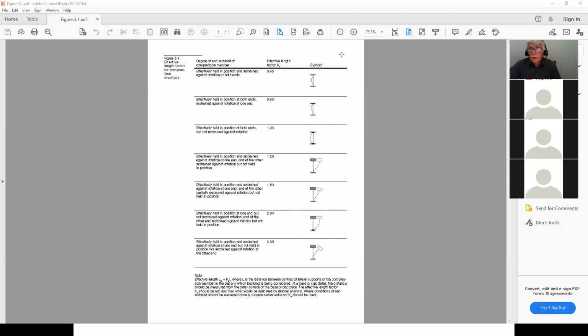In other words, if for example I have a foundation wall here, a big foundation wall, and I nail a nice piece of wood in there, attached to my foundation wall, and it's well anchored. And then I put my studs here like this. And then I put a good sheeting of plywood that will transfer any lateral load to here and then to the wall. Everything's braced. So then you don't have to worry about it.